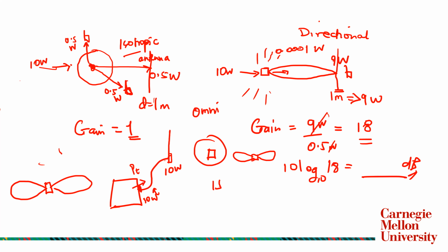I have another antenna that gives me a big, these are called radiation patterns. And I have another antenna that only focuses power in a very specific direction like that. This directional antenna, as long as the power going in is the same, will always have more gain. Okay, so I hope that is very clear to everyone.